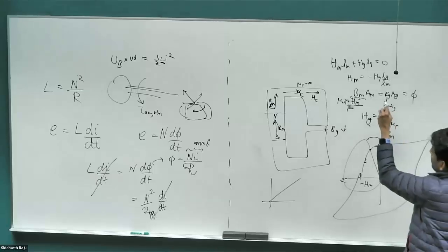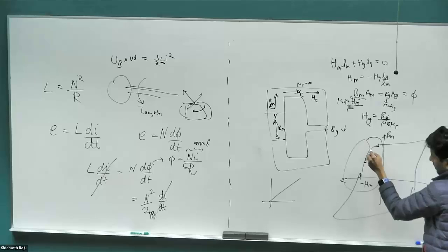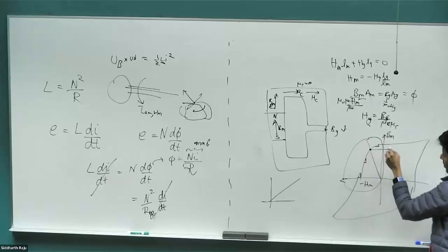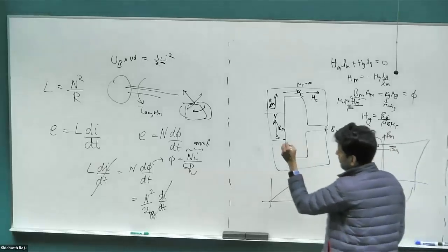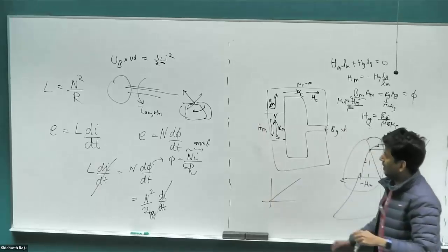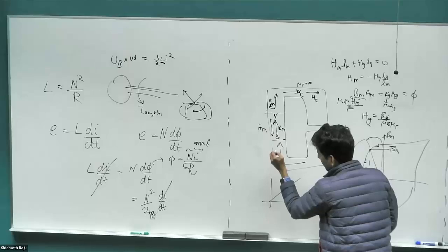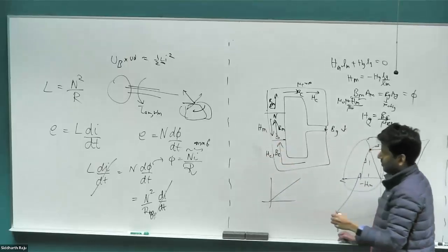So you would take this equation, substitute back into this equation, get a linear equation, and draw the load line wherever it intersects the BH curve. That is the value where your magnet B field is going to be, and the H field is going to be negative. So in a magnet, the HM is opposite BM. So it does sometimes get confusing. B core and H core are in the same direction, but HM and BM flip around.